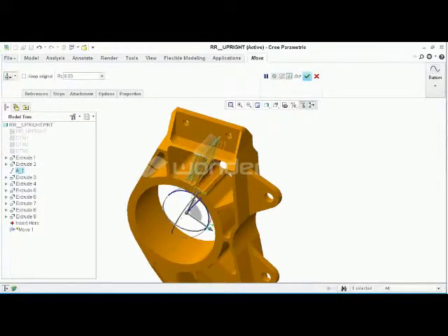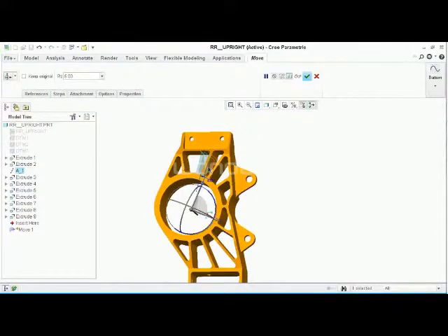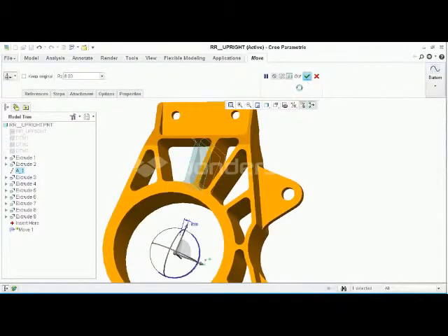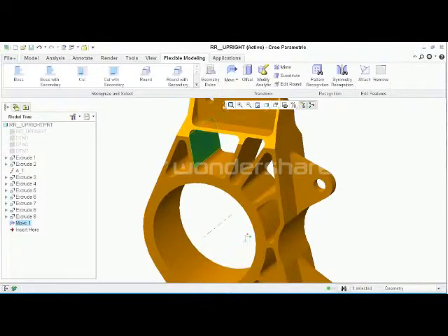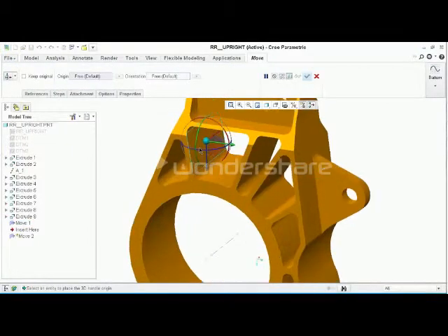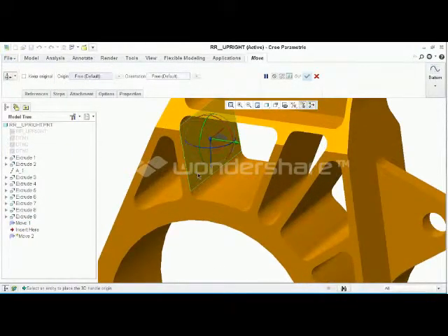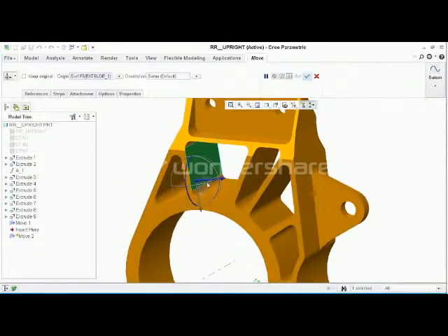Second thing I want to do is take this wall and thicken it up a little bit by also performing the move command. I want to move it normal to this surface right here. I'm just going to drag this out by some distance. In this example, it's going to be 1/8 of an inch. The idea is I really don't care how the model was originally built. I'm just operating purely on geometry, okay?